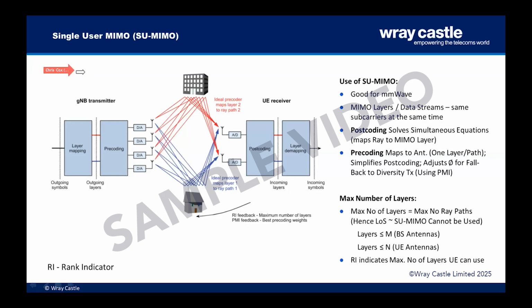Second distinction, the base station can't steer nulls towards antennas anymore because the antennas are way too close together. So, base station can't steer the nulls anymore. Both antennas are going to pick up something about everything that's arriving. However, the mobile has access to both antennas, so the mobile is capable of disentangling everything.